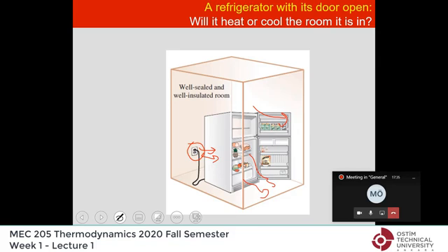So, okay, it went to the motor of the refrigerator, to overcome the frictions. And then at the end, the whole thing is converted to kinetic energy of materials, air, whatever. All will show up as heat. That is, all the energy consumed as electricity eventually will have to show up as another form of energy, which is heat. As a result, the temperature in the room will have to rise. Okay? So this is thermodynamically viewing things.